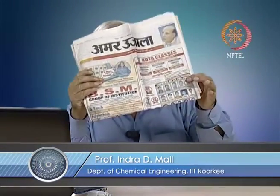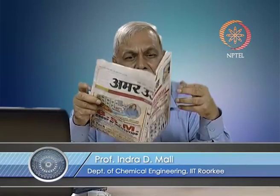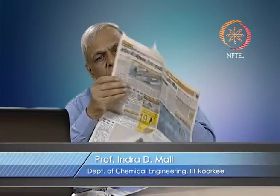These are some of the reasons why we need mechanical pulp in the case of newsprint. A lot of printing is involved, and so two-sidedness should not be there, because if you are printing on this side, the ink should not show through on the other side. That is very important in the manufacture of newsprint. That is helped by ground wood pulp, or the mechanical pulp, because it is finer. So these are some of the advantages.